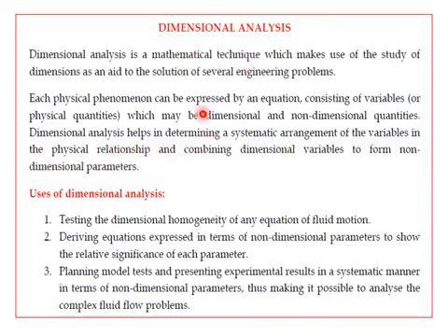So what is the use of dimensional analysis? Here we can test the dimensional homogeneity of any equation of fluid motion. Dimensional homogeneity means that the dimensions on the left hand side should be equal to the dimensions on the right hand side. You can derive equations in terms of non-dimensional parameters, give the relative significance of each of the parameters, and plan the model test. So model studies can be done and these experimental results can be used in a systematic manner to analyze complex fluid flow problems. So that's the use of dimensional analysis.